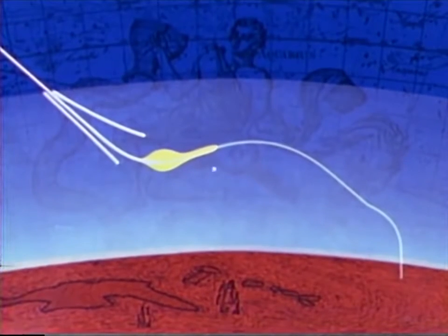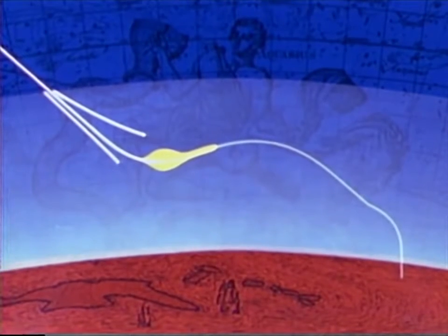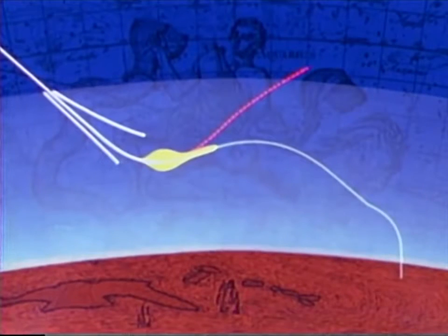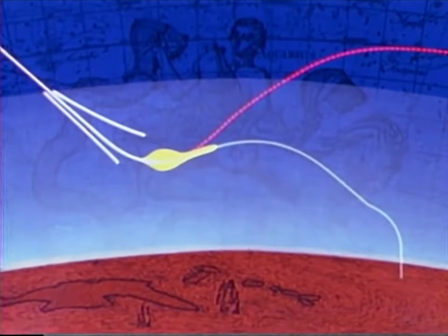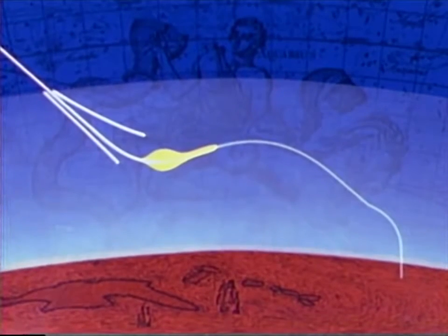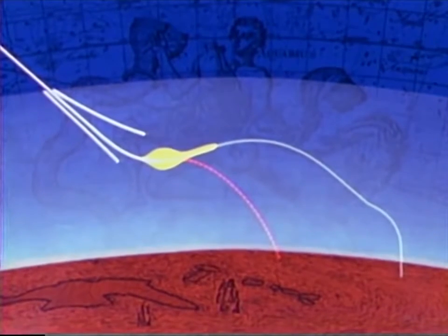During the first 70 seconds of this control period, any error or failure to correct an error could result in what is called, in great understatement, a non-recoverable situation. That is, too much lift up could put the spacecraft and crew into an orbit that would last beyond the lifetime of the command module systems. Too much lift down could take the spacecraft and crew beyond the stress and heating rate limits and result in destruction of the command module.